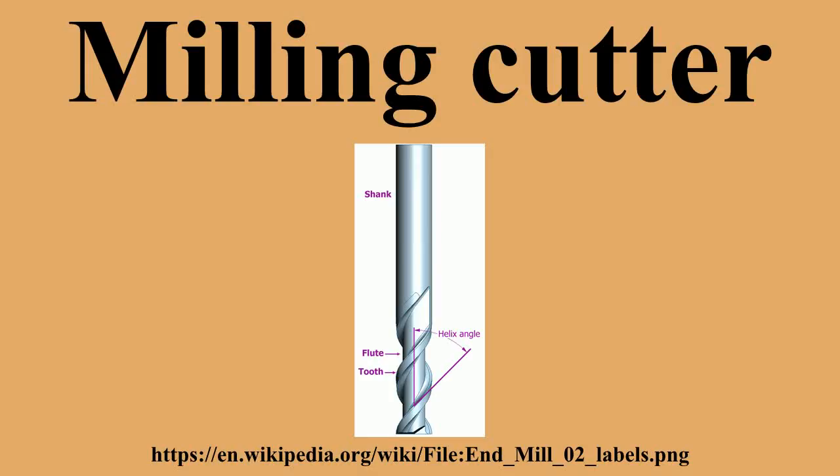In 3, 4, or 5-axis milling with a ball end mill, the work is handled readily by CAM software rather than manual programming. Typically, the CAM vector output is post-processed into G-code by a post-processor program that is tailored to the particular CNC control model. Some late model CNC controls accept the vector output directly, and do the translation to servo inputs themselves internally.